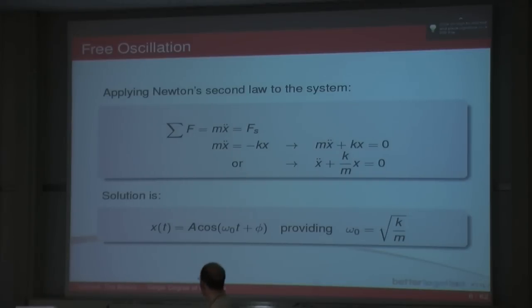If you think about it, if I've got a mass and I move the thing by 1 millimetre, it's going to oscillate with an amplitude of 1 millimetre. If I take the same mass and the same spring, considering it's a linear spring, if I move the thing by 1 metre, it's going to oscillate with an amplitude of 1 metre. But that initial condition, whether I move it 1 millimetre or 1 metre, is what I define to the system. And A will change correspondingly. But I can't work out A if I don't know those initial conditions. The same thing with phi. If I give it an initial velocity, I put it out half a metre, but actually push it, that will change how it oscillates, because it will change where phi is.